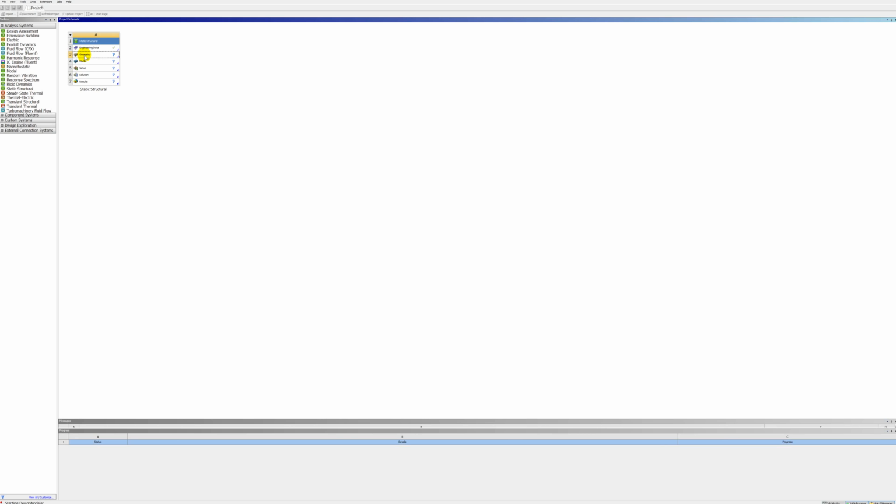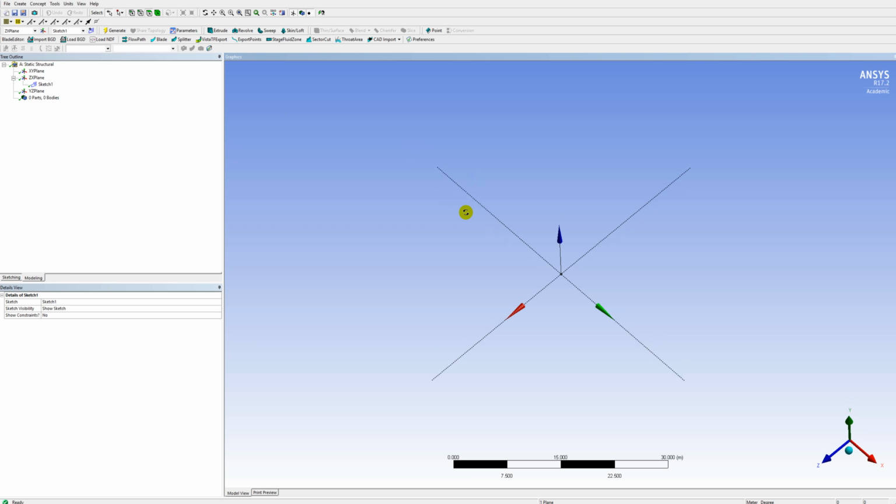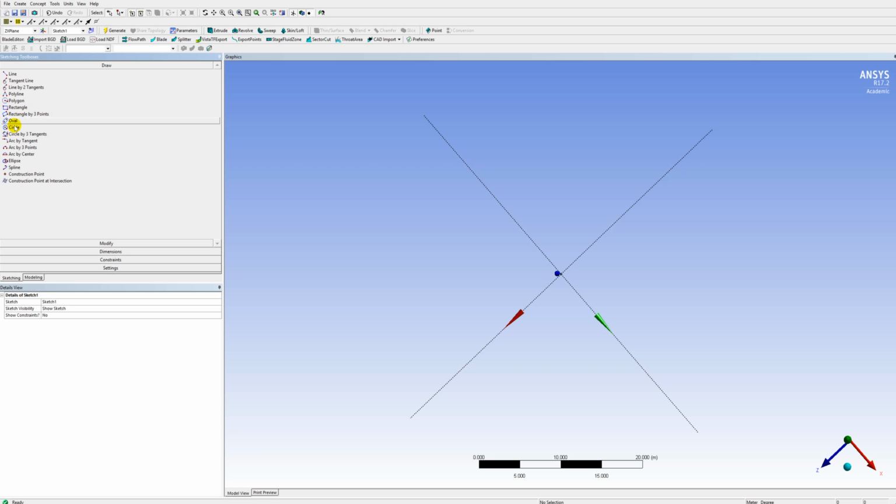The 2D sketch that we want to extrude for this casing is a circle with another circle inside of it. Select the ZX plane, click the New Sketch button, and then draw two circles centered at the origin. It's done via the Sketching tab, and circle, click at the origin, and click anywhere else. Repeat once, but put the second circle inside the first. Select the Units menu and then pick millimeters. Amateur rocket motor casings almost always use millimeters.